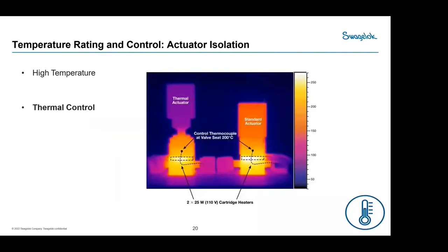One of the other factors that we've been talking about in the ALD and the conformity and yield is high temperature. Like I talked about earlier, people are designing to high temperatures so they can have better flow, better evaporation, better consistency, so they can run the processes at high temperature. So not only specifying the valves which go to higher temperature, but also finding the valves which are consistent at high temperatures, and what are some of the things that we can do to help with that. At high temperature, it's not only critical, but even harder to control the temperature, because now you have places where temperatures are high, there might be places where temperatures are low, and you can have issues like condensation or lack of flow or inconsistent flow.